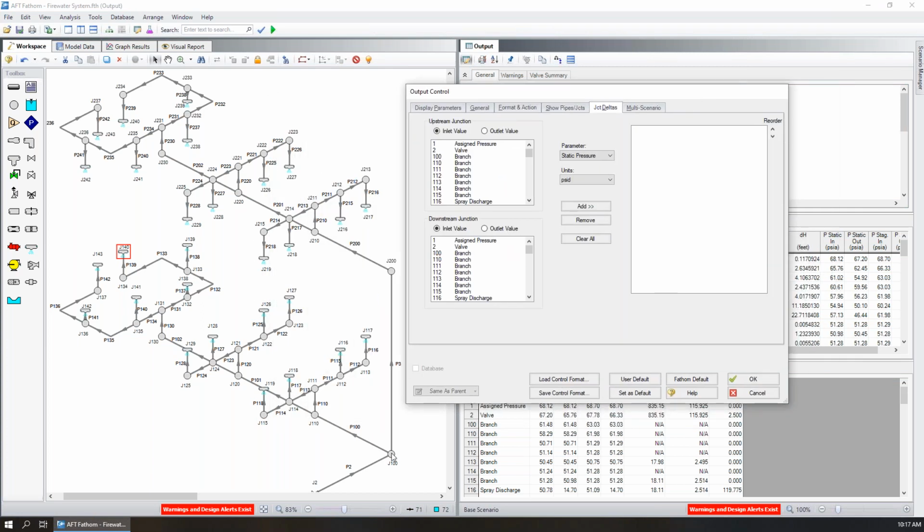So our first value is going to be the inlet of this branch, and our outlet is going to be this upper spray 240. We're actually going to use the inlet because I care about what it is at this point. If we set it to the outlet, it'll actually just set it to atmospheric since it is a spray discharge. We're going to look at the change in static pressure, but there's some other parameters that we can consider. Pressure change is usually the most common. And now we can also add a second junction delta for these lower sprays.